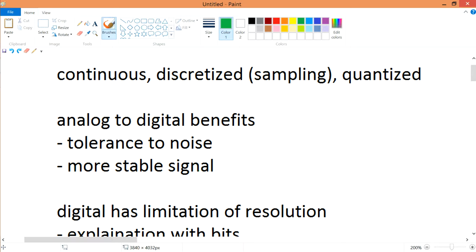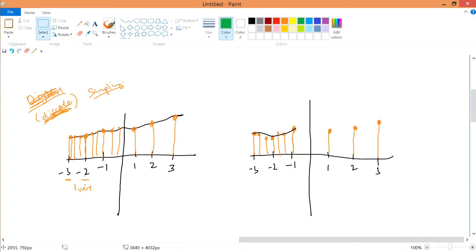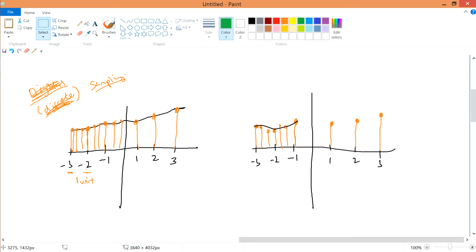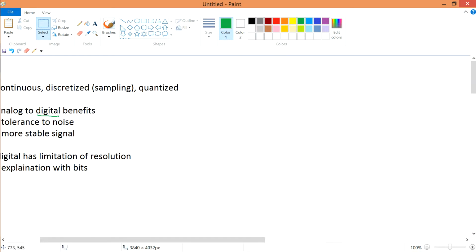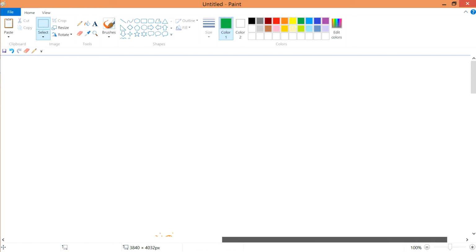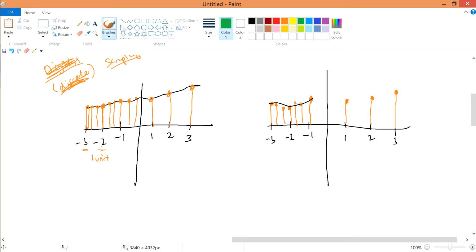However, one key thing is that the digital itself has limited resolution. As mentioned earlier, we said that we are going to come back here to the discrete sampling. Why do we say so? This is why we are talking about resolution. The resolution defines how many samples you are going to take. If we take more samples, the resolution will be better.